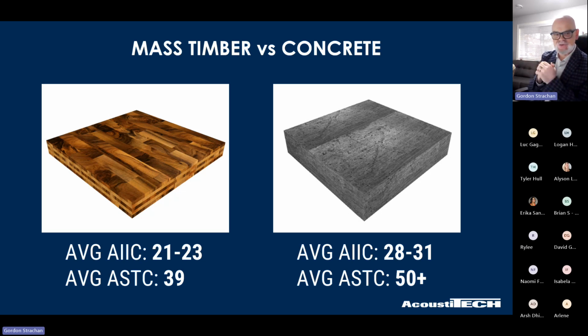So what do you have to do when you're treating the acoustics? You have to treat it on the top. You have to do it on the floor side rather than the ceiling side. And because the mass timber, we have to address IIC and STC, that's a lot more work. On the concrete side, like I said, one product is going to improve that IIC. We put one of our textile mats in there, you're done. You're sitting in your 60s, you're happy. But when we're talking mass timber, let's get right into it because it's not simple by any means.